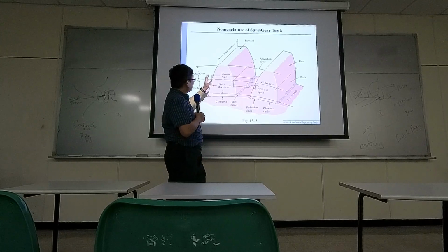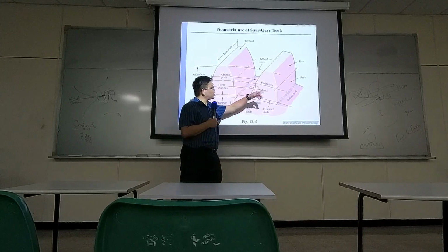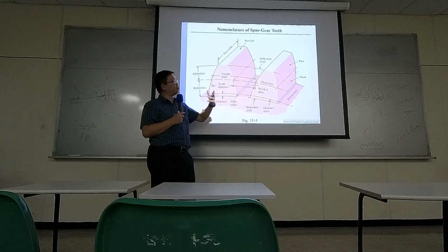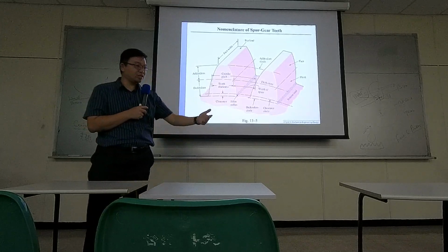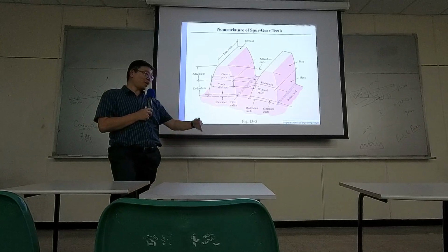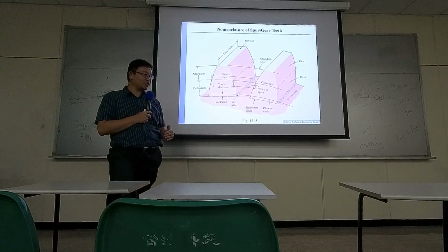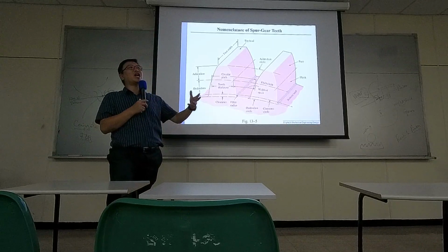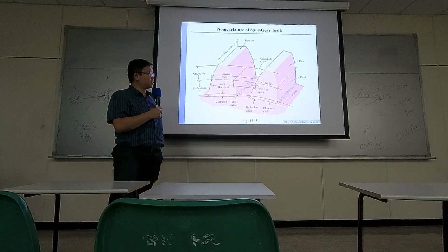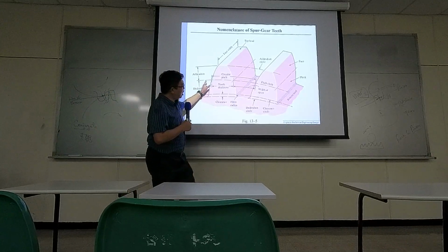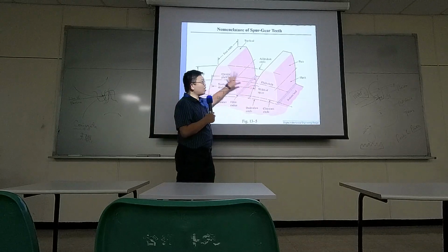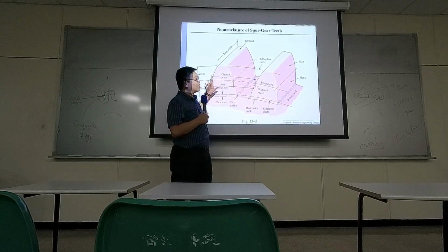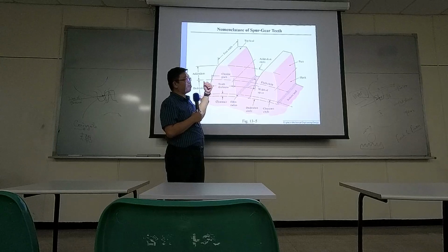Okay, if this circle is called a pitch circle, then how do we compute the pitch? Pitch is usually describing the distance from one pattern to the next pattern in some kind of periodic sequence. So along the entire pitch circle, between two neighboring teeth, how do we compute the pitch?